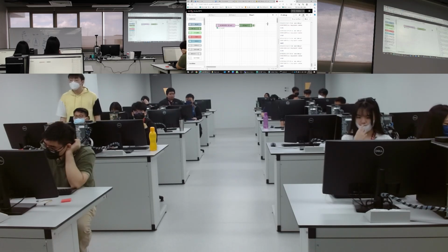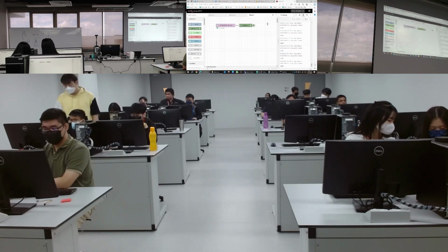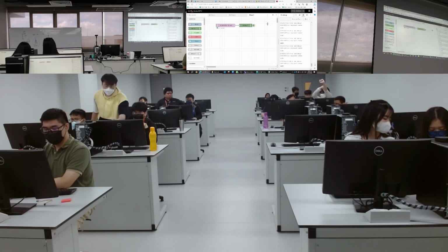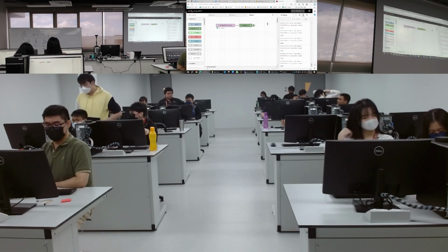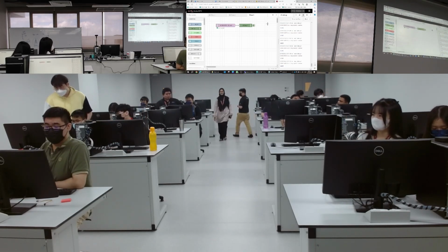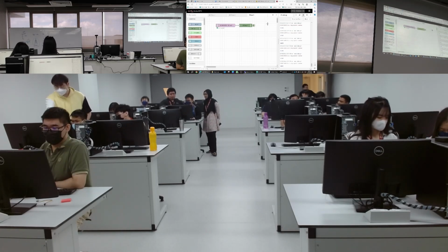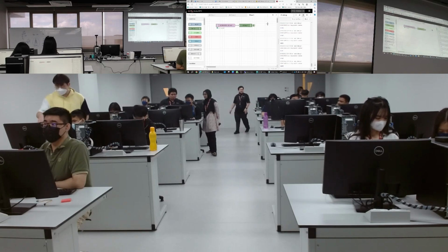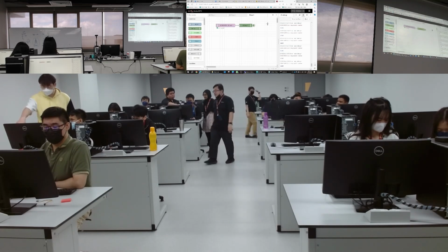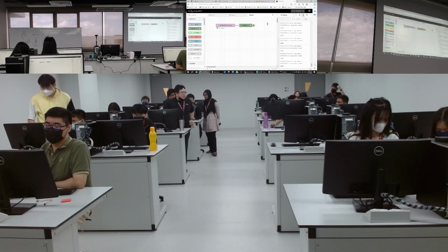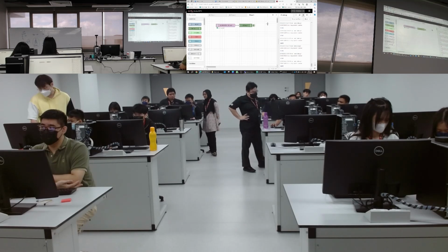So here you search MQTT. Yeah, that one. Okay, you search another one is debug. Okay, connect these two. Okay, done. MQTT. Setting this up. No, double click only. Then server, add. Okay, so we add a server. Open your code. Copy, scroll up. Copy the server. Broker. Copy, then you paste it here.